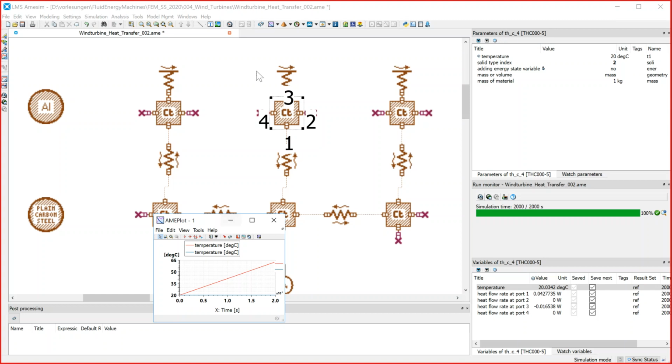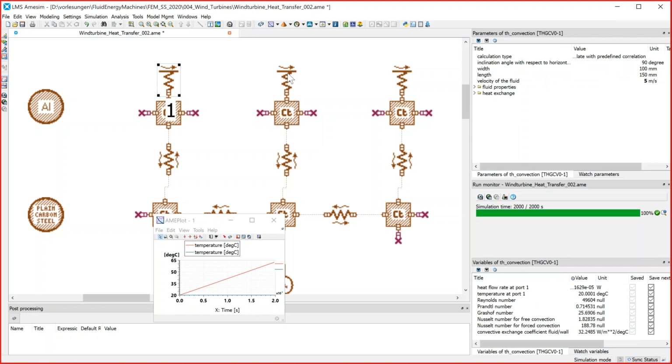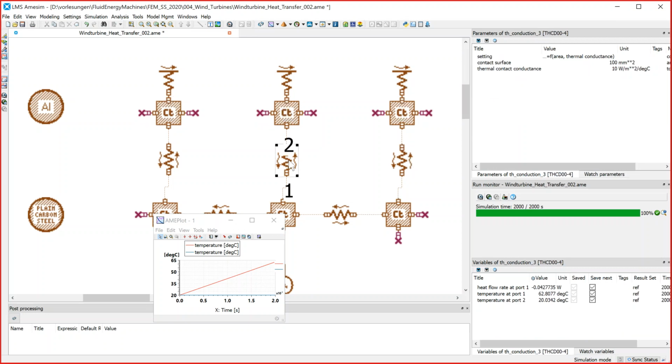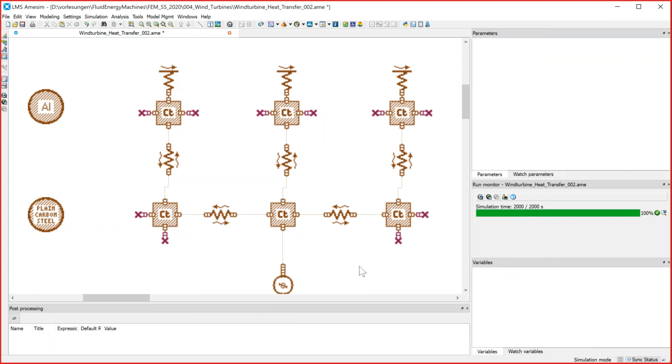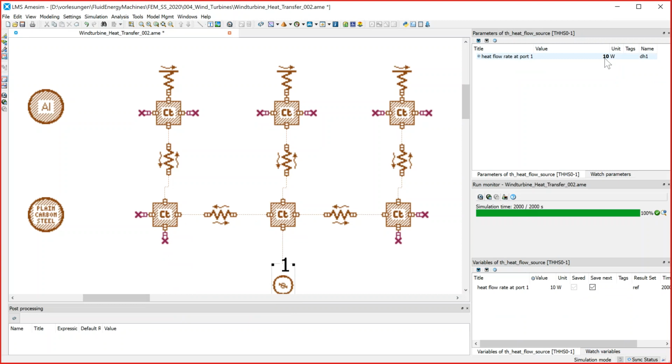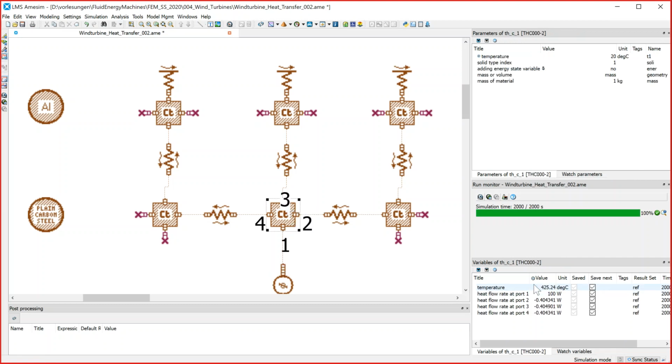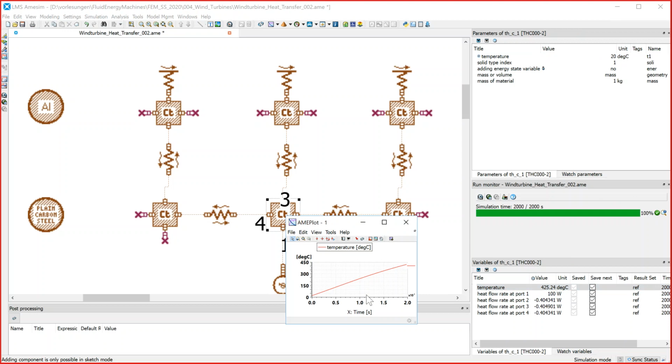Of course, all these values for geometry and for fluid flow and also this conduction connections, you have to change the values here a bit for the surface to get temperatures lower than 100 degrees. Now we are at a really high degree. If you have a lot of electric heating power here, if we have 100 watts, the temperature will be too high for our generator. Yeah, we will have 400 degrees, and the iron and the aluminium will start to deform.